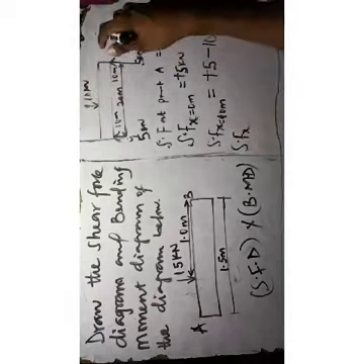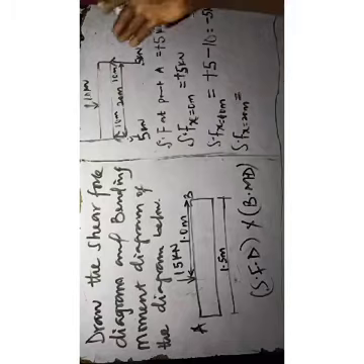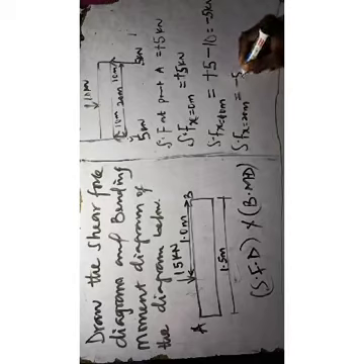Now the shear force also, when x is at point B, or let's say at 20 meter, the shear force there is very constant when you get here, and it comes back to 5. That'll be minus 5 plus 5, right? And that is equal to 0. You will say minus 5 plus 5, that'll be equal to 0 kilonewton.